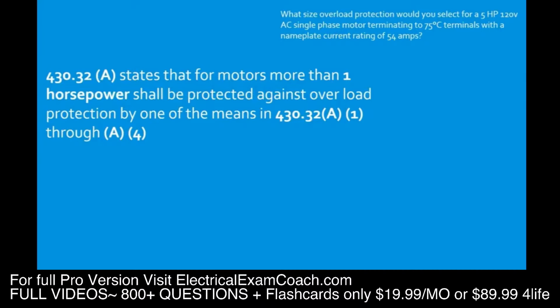So a way to simplify it, if your motor is not marked with a service factor of 1.15 or greater or a temperature rise of 40 degrees C or less, it's going to fall under the all other motors category and your demand factor is only 115%.